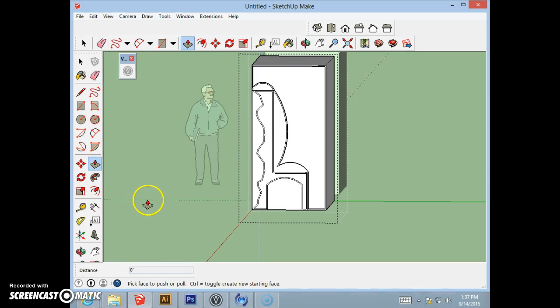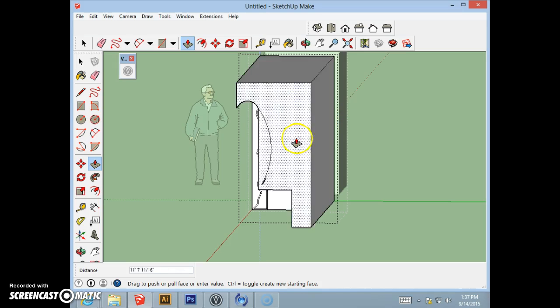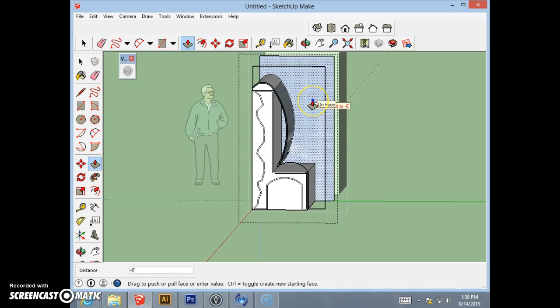Not only with the extrude tool can you extrude stuff, but I don't know if it's a word, you can detrude things. Make the extrusions go all the way away. So what I'm going to do is select this surface and just push it until it gets back on that back wall. And it'll give you a little warning when it gets on that back wall. And you don't want to go past it because you'll start re-extruding the other direction. It gets a sort of glossy look when you're on the back face. Just click there and it disappears.